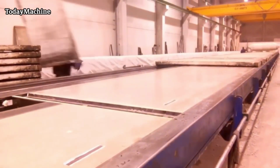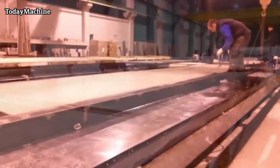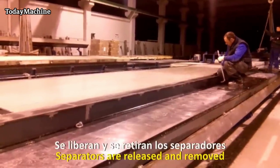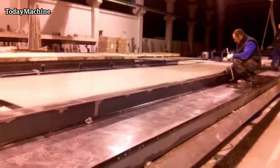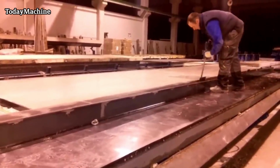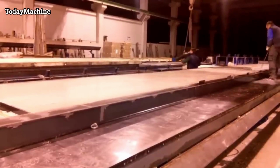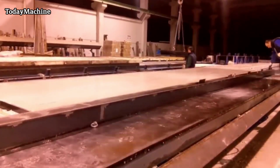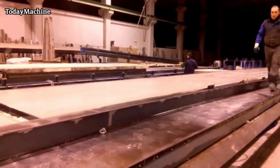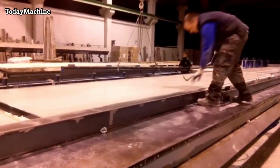Once the concrete has sufficiently cured, the next step involves the release and removal of the separators. Careful attention is required during this process to prevent any damage to the panels. The release agent applied earlier plays a crucial role here, allowing the panels to detach from the separators smoothly. Proper handling during this phase is essential to ensure that the precast panels maintain their structural integrity and dimensional accuracy.